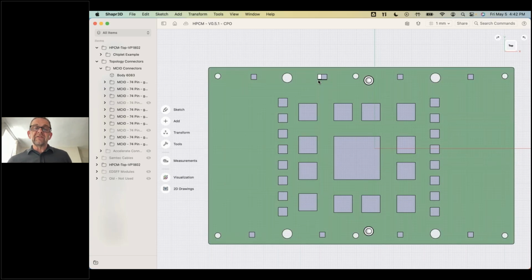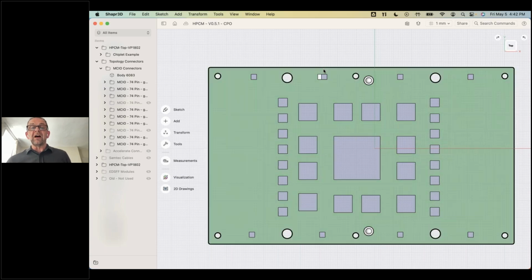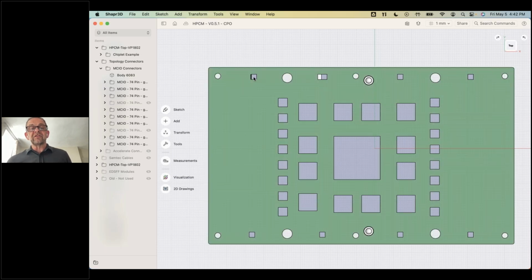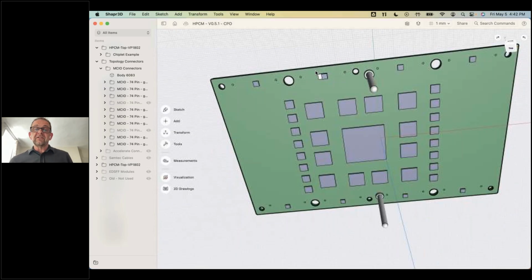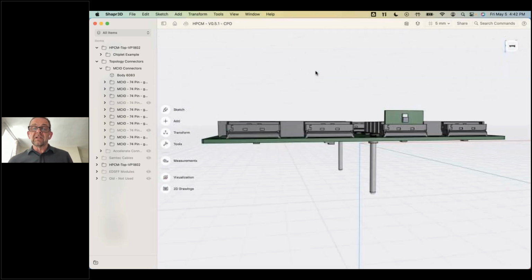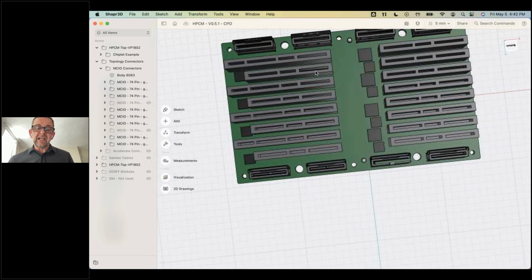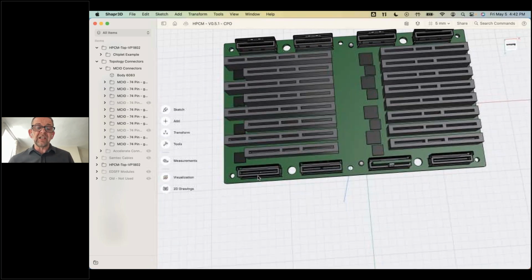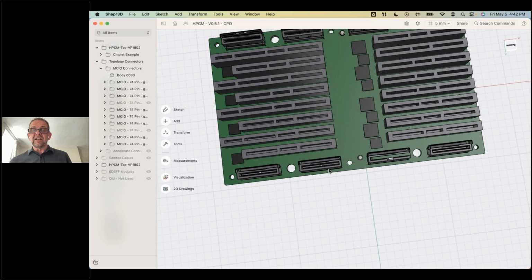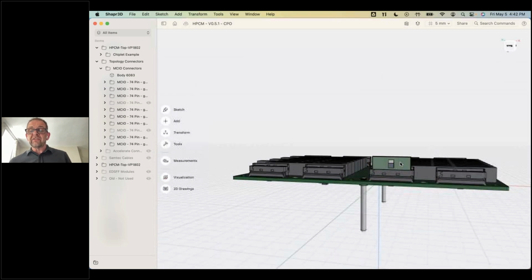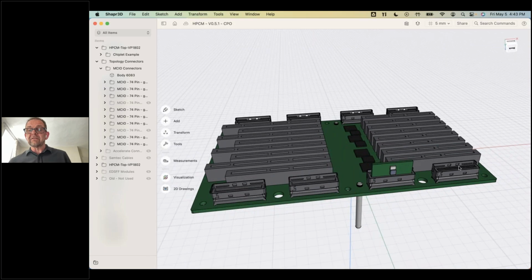Here we can see the stacked optical die and electrical die all mounted on the top. One would assume the light would be launched out of the back of the optical die through that hole I showed you. And here we have just the electrical die. If I switch over into the model and look at the connector side, now it's on the bottom, you can see the little hole bringing the light through on these. On this one, I've got a little paddle card PCB plugged in with the optics chip on it for an active optical cable. And here is just a regular electrical interconnect.